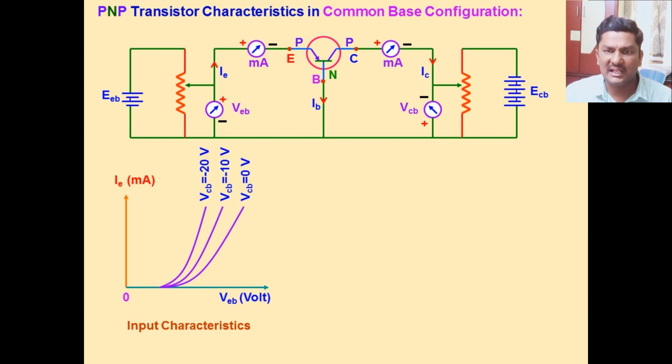When p-type semiconductor and n-type semiconductor are suitably joined, a PN junction diode can be formed. So there is diffusion of charge carriers from one region to another, and at the junction a potential barrier, the depletion layer, is formed. The potential difference across the depletion layer is the potential barrier. So for silicon the barrier potential is about 0.7 volt, and for germanium it is about 0.3 volt.